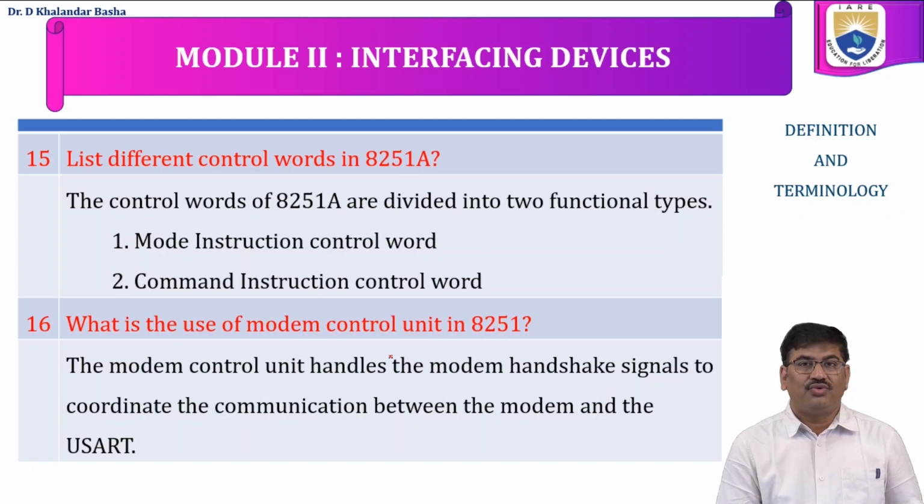What is the use of the modem control unit in 8251? The modem control unit handles the modem handshake signals to coordinate the communication between the modem and the USART. So if the data transmission has to take place through the modem using the handshake signals, then we have the compatibility of 8251 with the modem control.